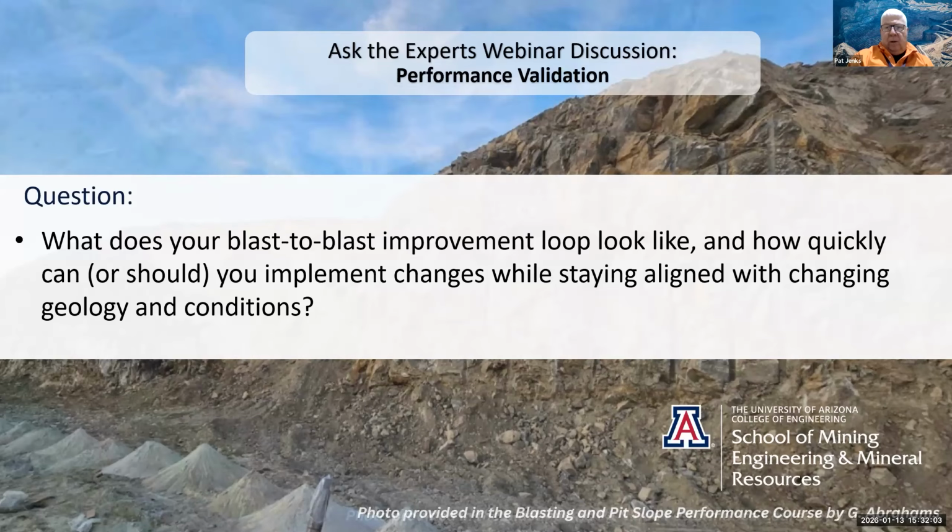But ultimately, one of the approaches I like to follow is to start by looking at the videos of the shots for the bench. Start with the production shots, then follow up by looking at the trim shots. Do you see any performance issues in the blast pattern? Is there evidence of backbreak in the video? Do we see any geological influences from faults or lithologic contacts that may influence that shot performance? Do we see energy troughs at the margin of the shot or the back? Do we see debris coming off the high walls above the shot?